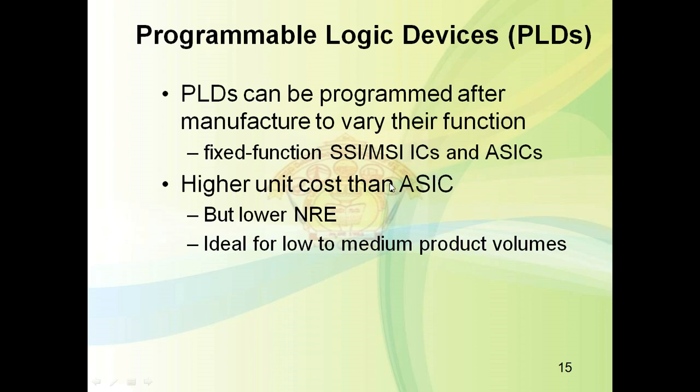But in case of ASICs, it is designed for a particular function. It will have very minimum feature size, interconnections will be minimum, no extra devices will be there. Hence area will be small, density will be more, and hence that will have low unit cost. But in case of PLDs, it will have more area. It is designed for general purpose, and more extra devices will be there.